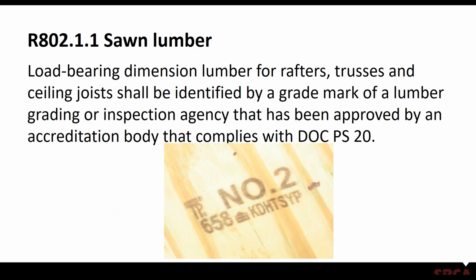Okay, so moving along, obviously, if you're working with lumber, the code requires that any load-bearing dimension lumber that's used for rafters, trusses, ceiling joists, studs, floor joists, shall be identified by a grade mark of a lumber grading or inspection agency that's been approved by an accreditation body that complies with the Department of Commerce Product Standard 20. We won't get into what all that is, but basically you need to have a grade stamp.